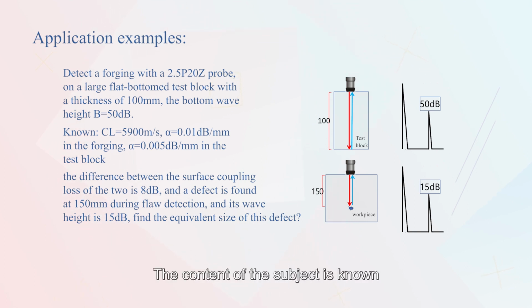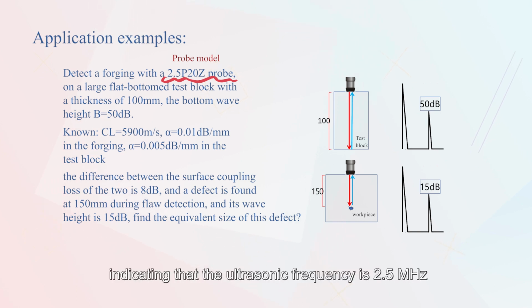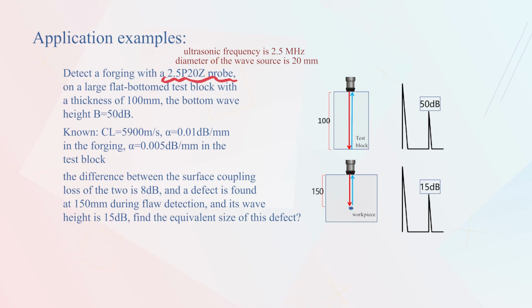The question states that the probe model is 2.5P20Z, indicating that the ultrasonic frequency is 2.5 MHz and the diameter of the wave source is 20 mm.